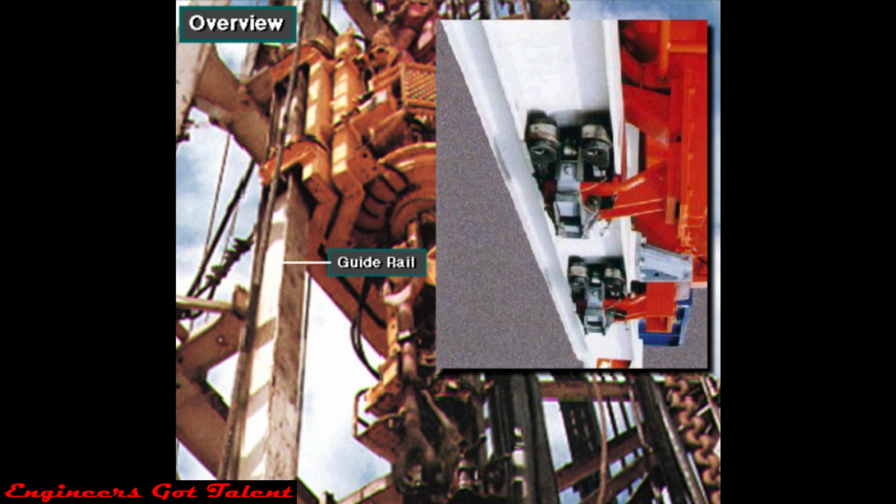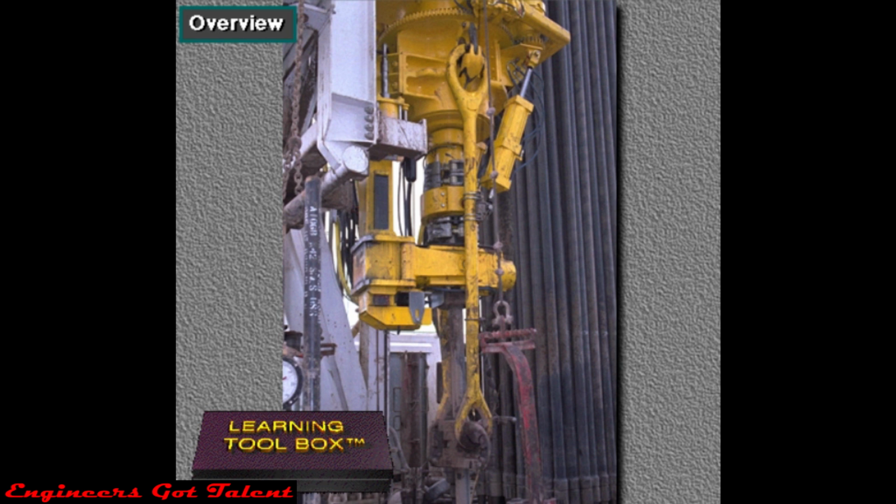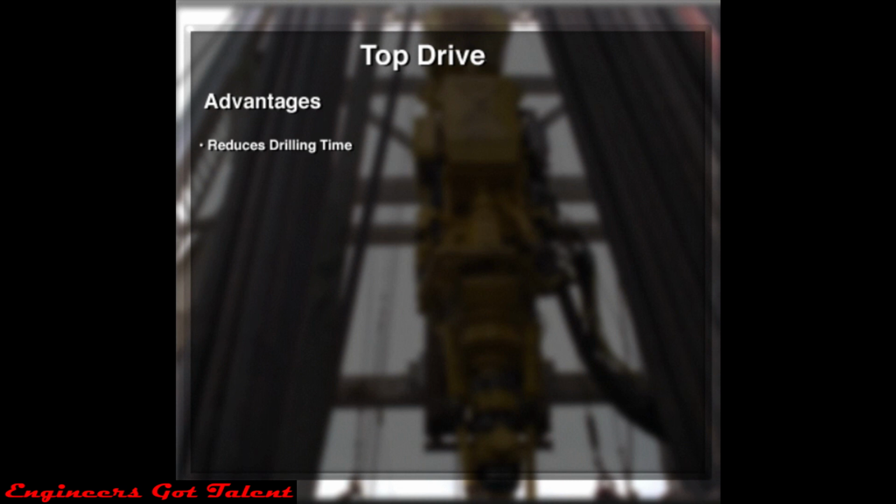Crew members attach the top drive to guide rails or tracks, which keeps the whole unit from rotating. With a top drive, the rotary table does not rotate the drill string. The most important benefit of a top drive is that it reduces drilling time. It also rotates the drill string more efficiently than a Kelly and rotary table system. Further, it handles stands of pipes more efficiently.